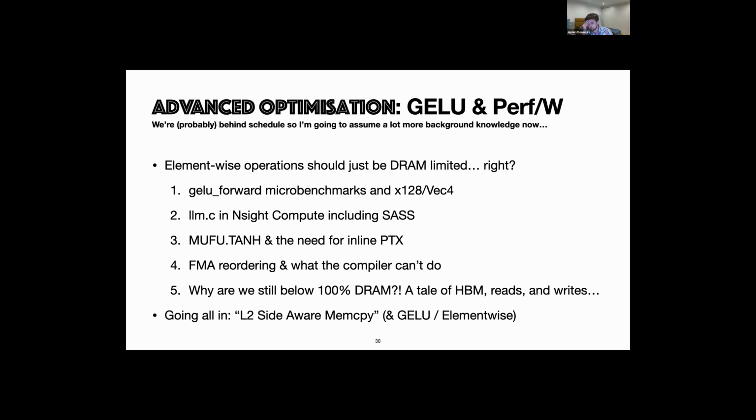I'm not really able to explain why it matters and what optimization you can do with it, but if you've got a kernel that only reads from DRAM, you might be able to reach 95% of the speed of light, or if it only writes to DRAM, 95%. Whereas if you're doing a one-to-one read to write ratio, because there's some overhead in HBM for changing between reads and writes, you might only be able to reach 90%.